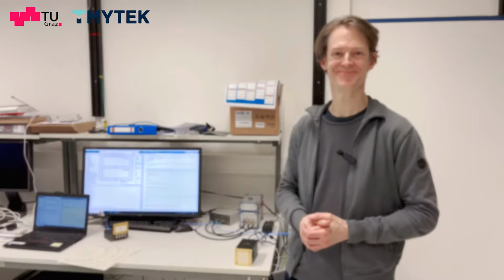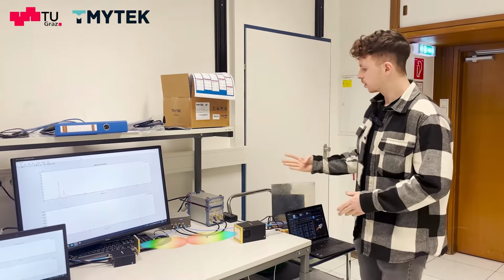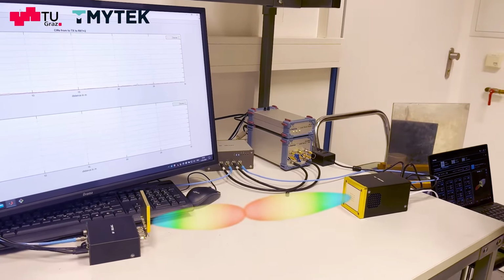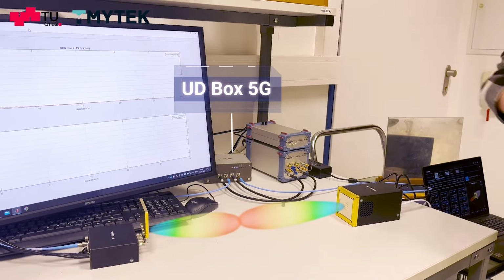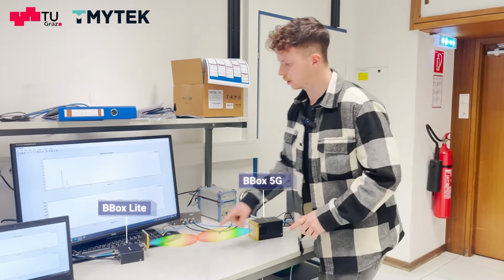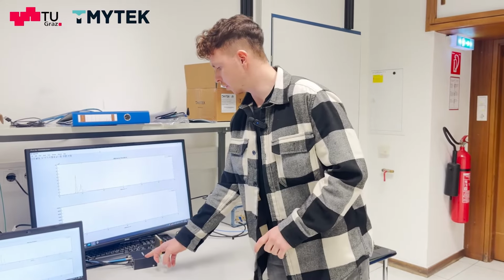Thank you. Hello, my name is Patrick and I'm going to show you the channel sounder we have built up at our institute. For that we have needed the products created by TMYTEK. You can see here the channel sounder. We have a signal generator that generates our sounding signal, and this signal is up converted by the UD box from TMYTEK. And this signal now is in the mmWave regime, and for that we need mmWave antennas and beamformers. And these two we can see here. Once we have a transmit beamformer and once a receive beamformer.